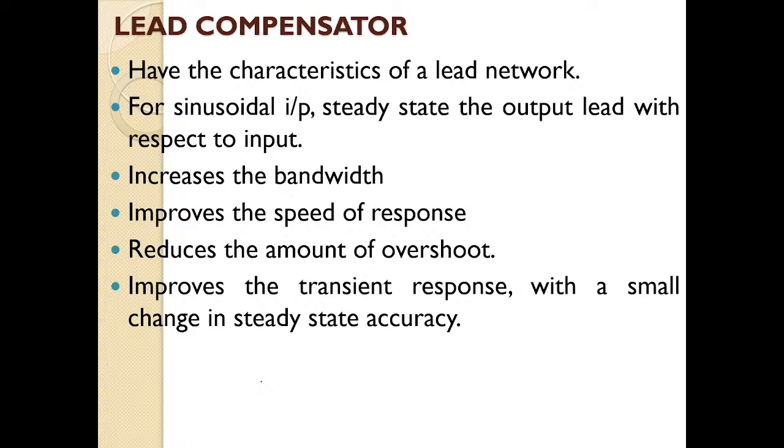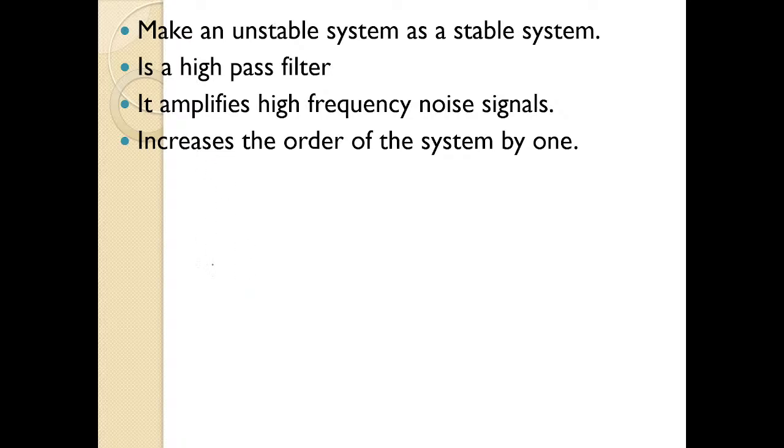This lead compensator is usually used to make an unstable system stable, and it is essentially a high pass filter. So it amplifies high frequency noise signals. Since it's a high pass filter, it amplifies high frequency noise signals.